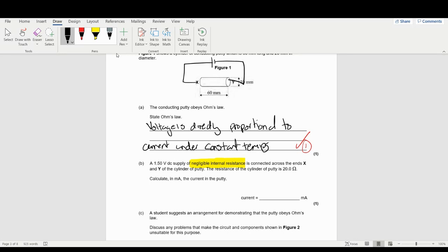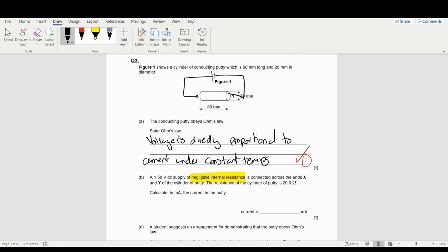So this is literally what the circuit looks like at the top. There's no other things here. So I've got my total resistance is 20. My voltage total is 1.5. So it's going to be I times by 20. So I equals 1.5 divided by 20, which is going to be 0.075 A, or 75. This is where it's important, the units here. Okay, 75 milliamps.